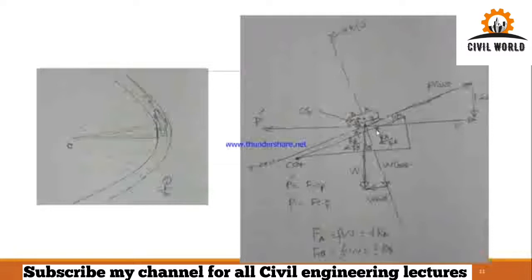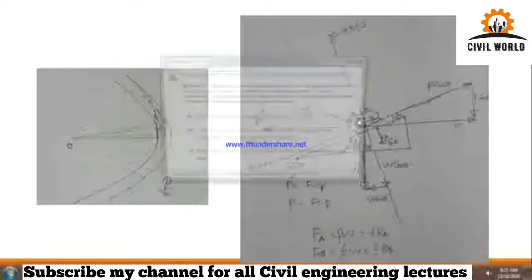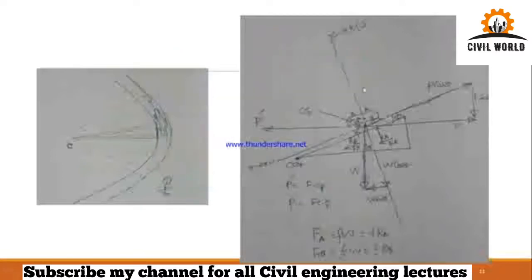Now there are two tires. One is tire B and the other is tire A, and RA is the reaction of the road or ground on tire A, which is acting upward along the y-axis, and RB is the reaction of the road on tire B, which is upward. Similarly, FA is the friction produced due to the contact between tire and road, and FB is also the frictional force produced due to contact between tire and road. These frictional forces FA and FB are directed toward the center of the circle.